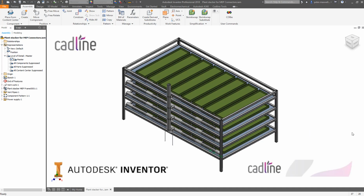Okay, so today we're going to be looking at the MEP connectors that we can attach to our models during the Inventor BIM exchange. Those MEP connectors will create an actual physical connection that Revit will understand, and also take across the information, the metadata, which is the important bit for BIM.